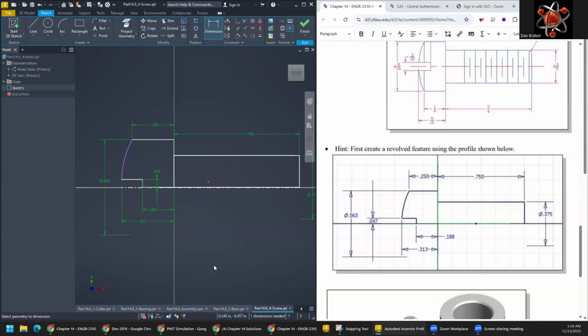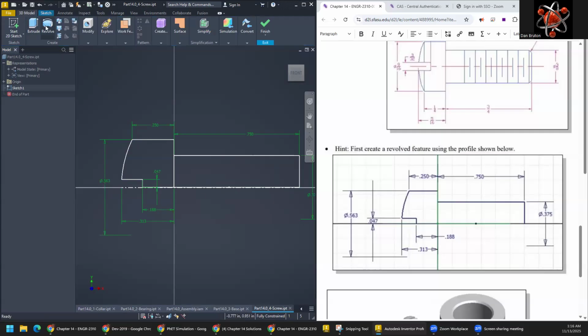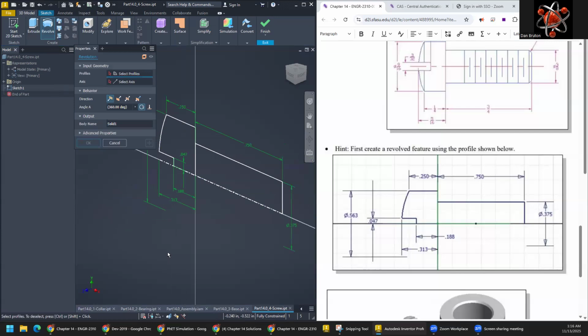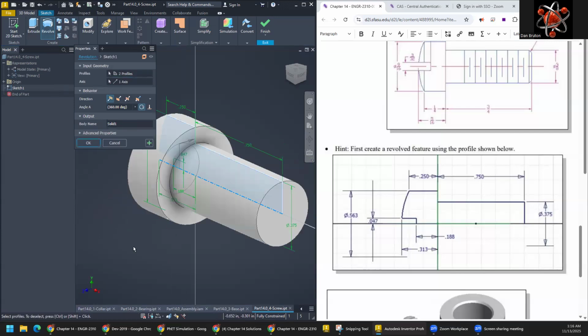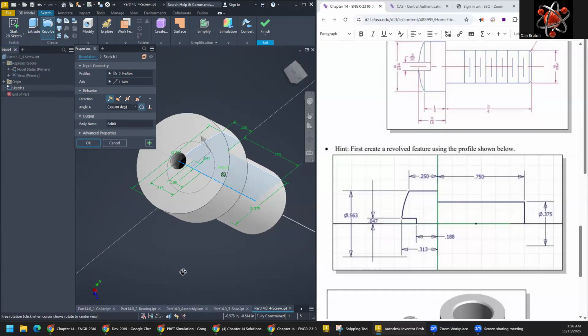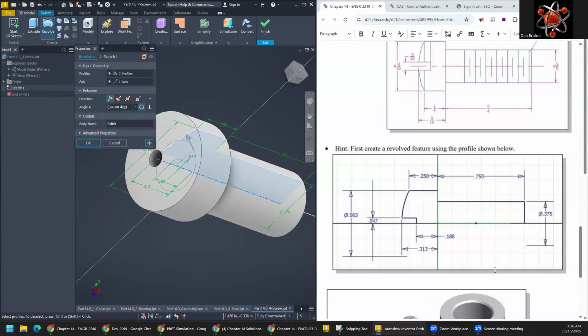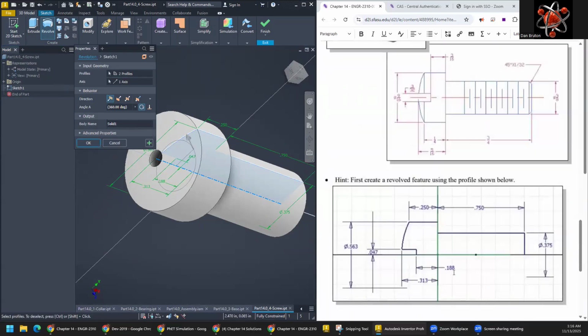All right. Now, the other thing that we need to do is make sure this is coincident with that. So let's see if it will let me do a coincident. And then that locked everything in, and now we're fully constrained. We can go about our revolve. And I just like how it's supposed to automatically do that, but it really didn't. And it recognized something about the axis right away. That's good.